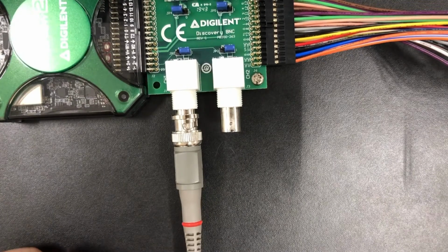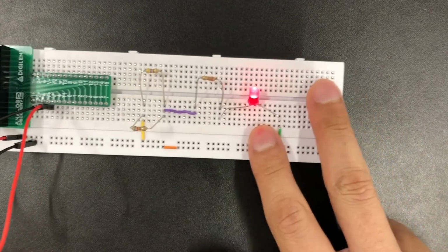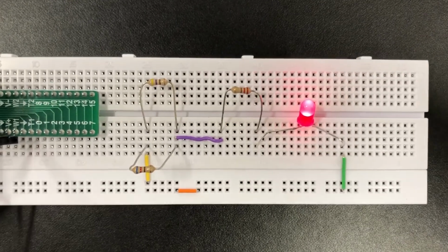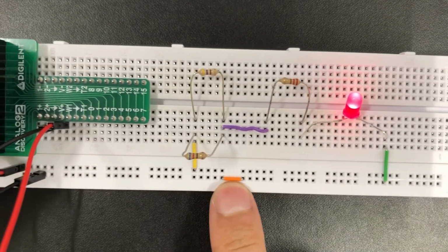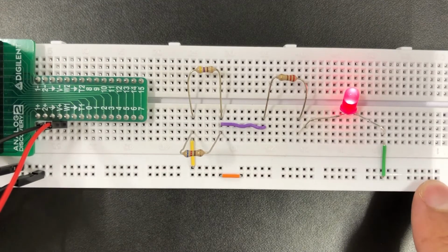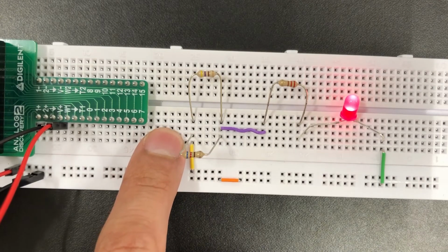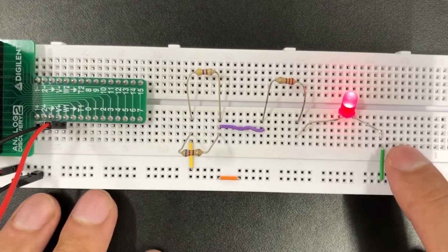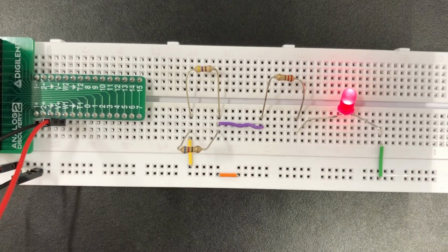So now that we've got the oscilloscope probe connected, we can move on to where we want to measure on the circuit. Now you can see that I've already got a circuit going, and you'll notice a few connections that I made. I did make this connection so that I can continue the ground column onto the lower half of the breadboard. And I didn't do the same for the power supply because my circuit begins on this side of the breadboard, but my circuit ends on this side of the breadboard. So this green wire connects to ground, and this jumper wire will continue that connection.